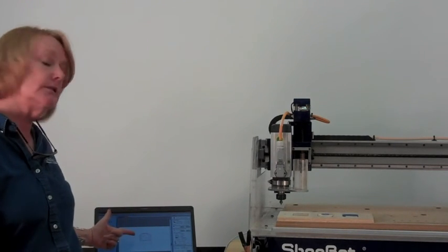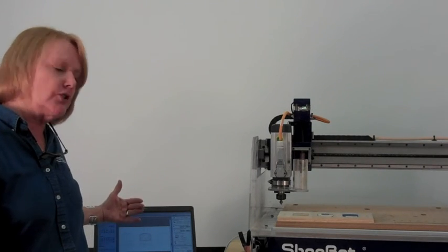So, to summarize what we have just done, we used computer-aided design, or a CAD program, to say what we wanted to cut out, our reverse S, and where we wanted to place it on the material. We then used CAM, or computer-aided machining, to say how we wanted to cut it out. We created a tool path, and then the ShopBot CNC machine fabricated our stamp for us.